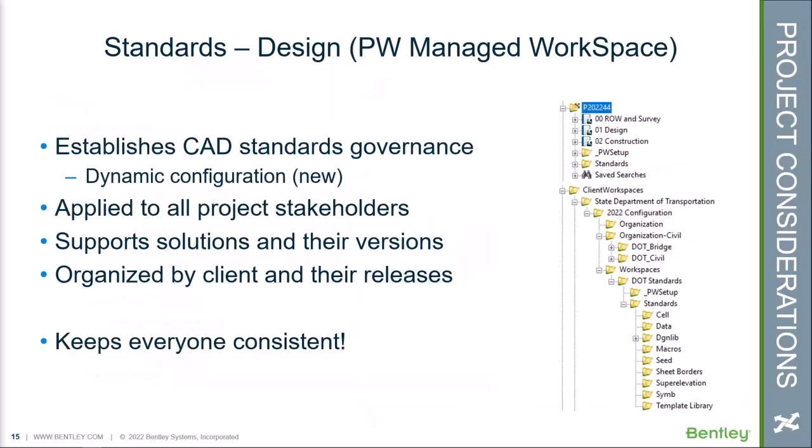And in this instance, we used a ProjectWise managed workspace. For those that are unaware, it just establishes some governance on our standards. It's making sure that symbologies are being adhered to across the design team. And we did leverage the dynamic configurations, which for some of you, you may be unfamiliar with. That's a new methodology to simplify the way we can handle those workspaces within ProjectWise.